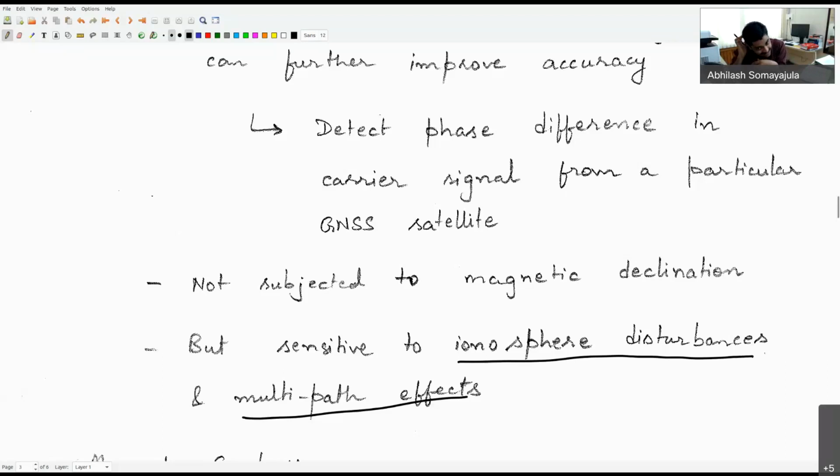That is why, as I said, when you have multiple paths coming in, you now have a flipping model. Your GNSS is believing itself to be at one location at one time, switching to a different location at a different time, and switching back at the next instant. So the switching phenomenon can happen.